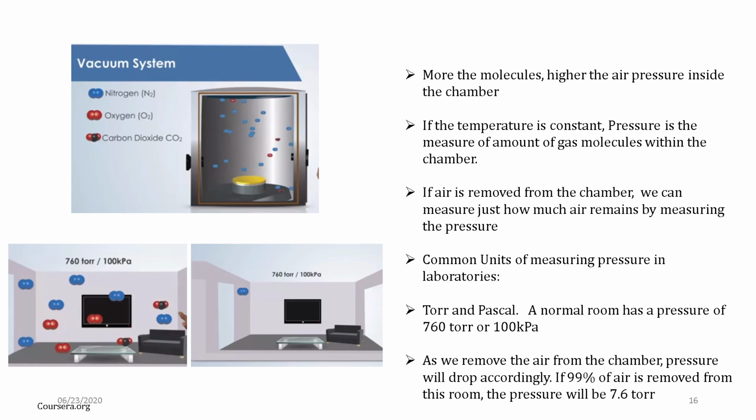We need to work with very high purity source material. As I said, if you have more molecules, then you will have higher pressure and you do not need it. Considering the temperature is constant, pressure is the amount of gas molecules present inside the chamber. So if air is removed, we measure how much air remains by measuring the pressure.